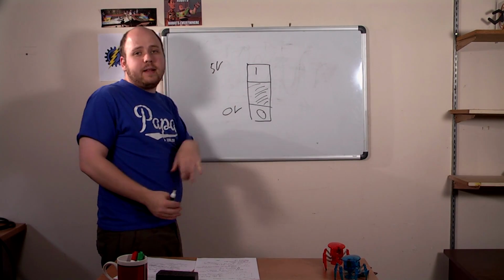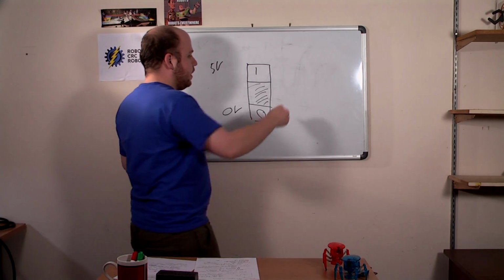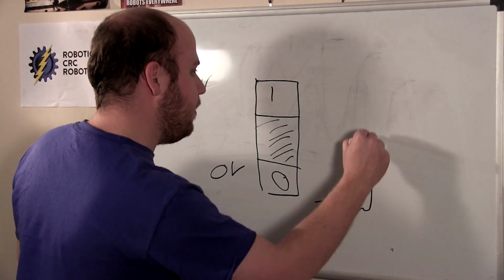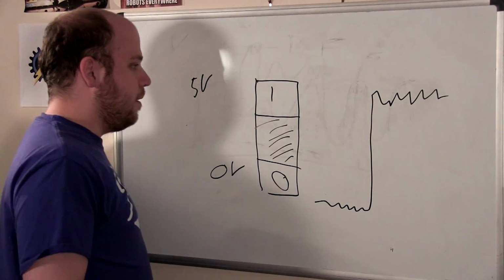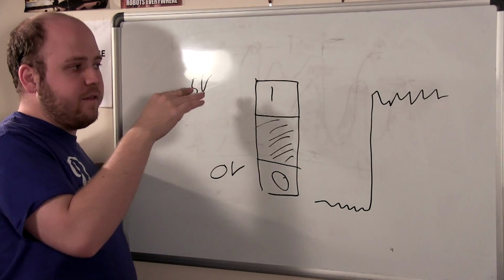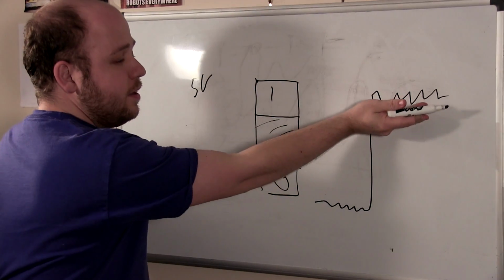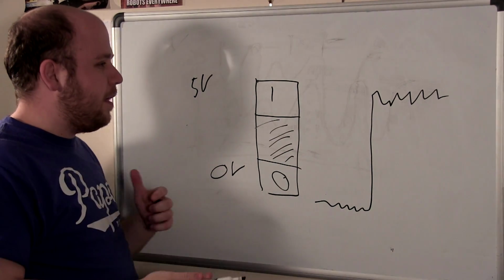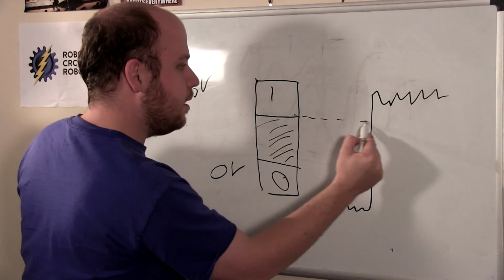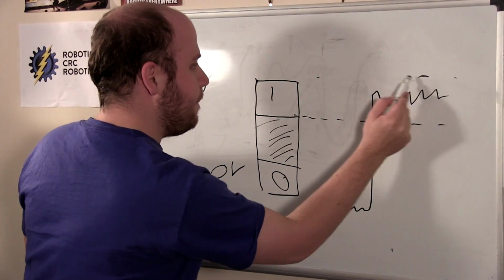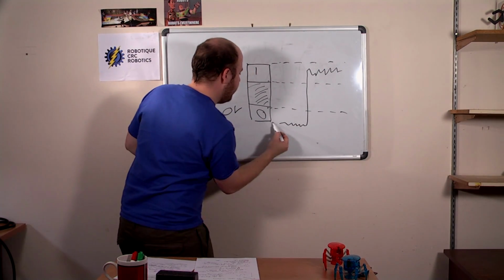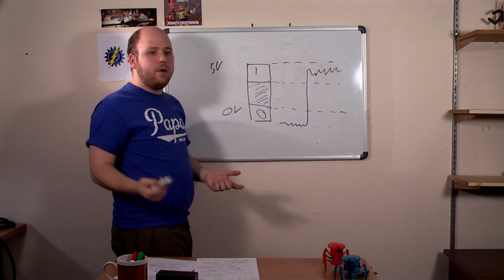Why did we put a dead gap over there? Well, let's say that your digital signal is not actually perfect 0 and perfect 5 volts. So you're having some noises that you catch from the environment or anything, but it's still within the level for 1 or within the level of a 0. So hence you're protected from that noise.